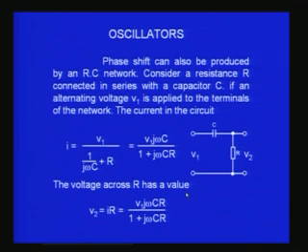So the voltage across R has a value V2 equal to current into resistance, again Ohm's law. So I into R. Now if you multiply this I by R, you get V1 j omega C R divided by 1 plus j omega C R. So you can get the value of the output voltage with reference to the input voltage when I apply it across a simple CR network.